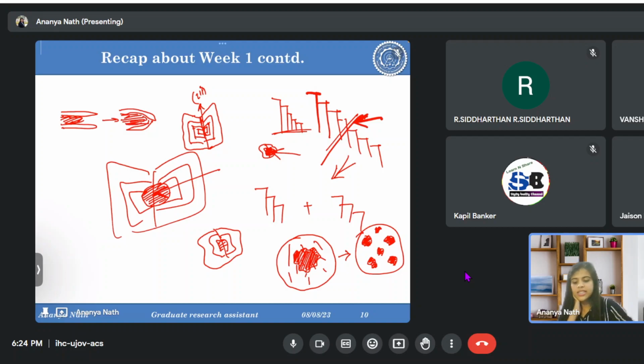And this is not like adding any modifiers, but yes, we can add modifiers to make this solidification even faster. But this is the normal habit of aluminium, that it will solidify faster, and we can even increase the speed of this solidification by adding some modifiers. There the modifiers were playing the important role of changing the growth site of silicon. Here they are just helping the aluminium atom to solidify faster.